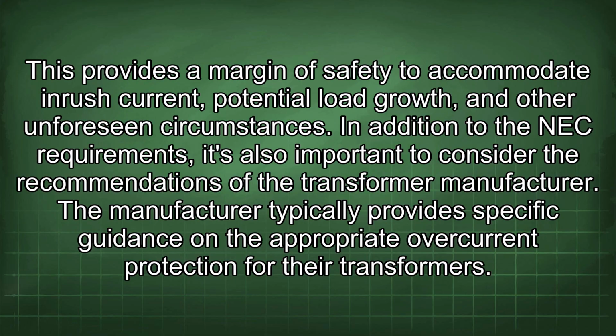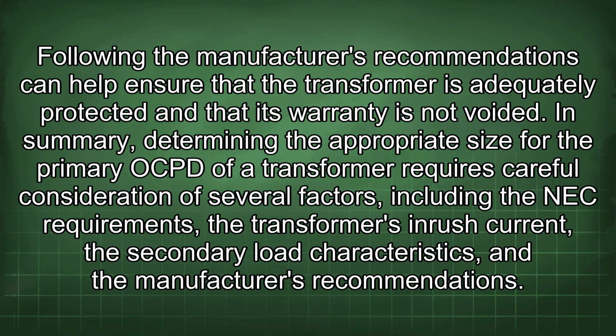In addition to the NEC requirements, it's also important to consider the recommendations of the transformer manufacturer. The manufacturer typically provides specific guidance on the appropriate overcurrent protection for their transformers. Following the manufacturer's recommendations can help ensure that the transformer is adequately protected and that its warranty is not voided.